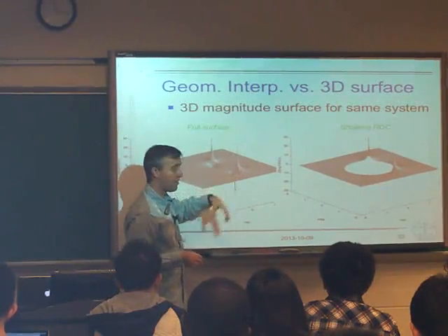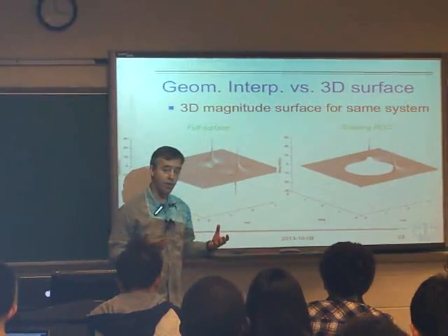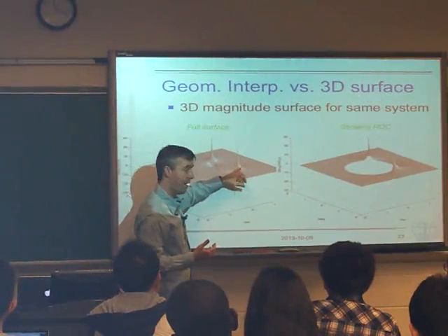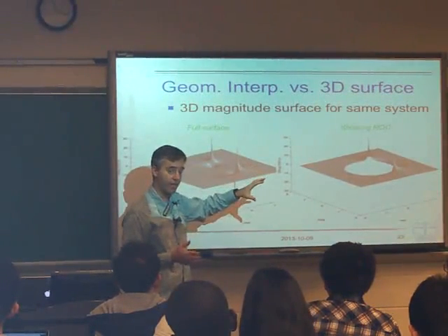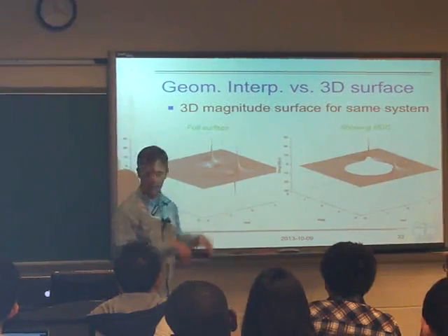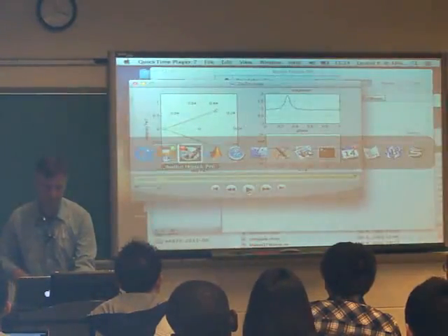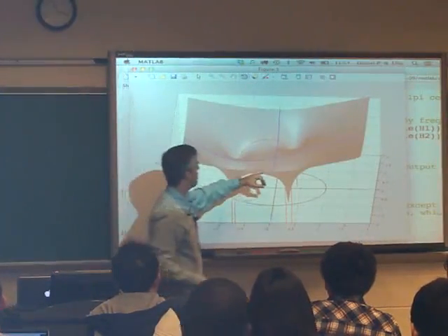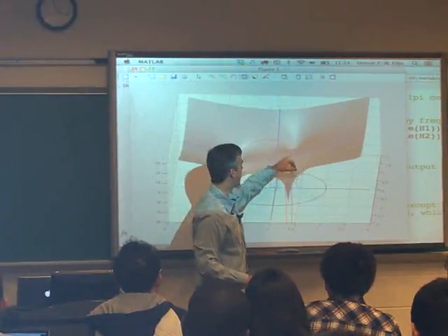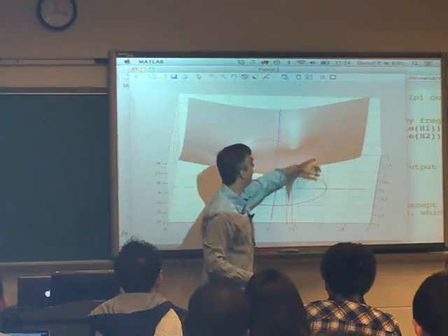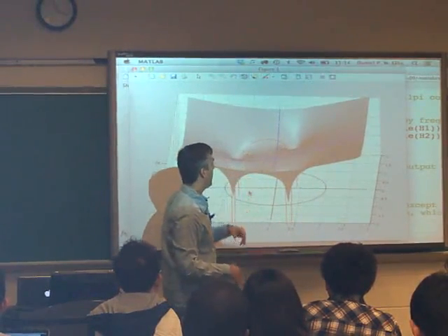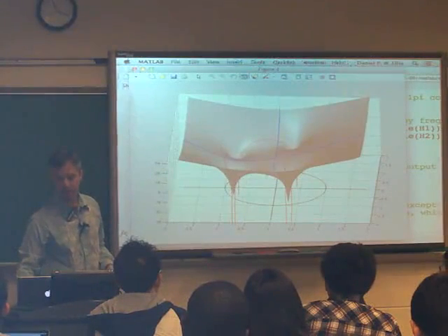These bumps are the same thing as what we just talked about in the geometric interpretation. This surface here is nothing other than the product and ratio of those vectors. If we just had the zeros, like in this one with just the 4 zeros in it, this surface is just the product of the lengths of the vectors from the 4 zeros to every point on the z-plane. And for the red line, it's the product of the lengths of vectors to the points on the unit circle. And this is the log of that thing.